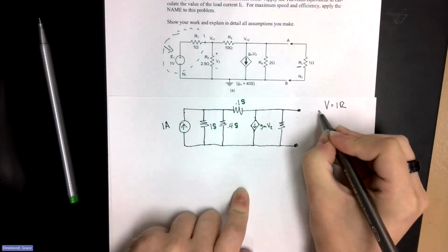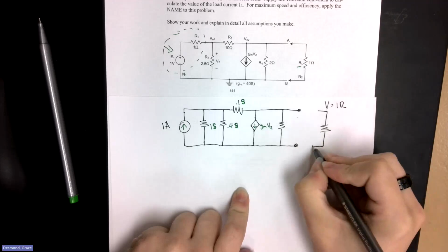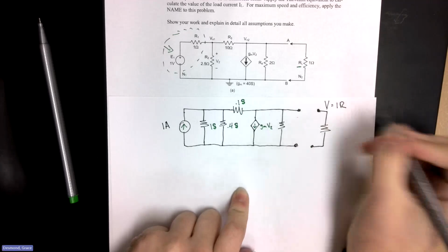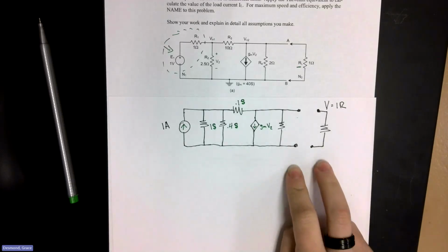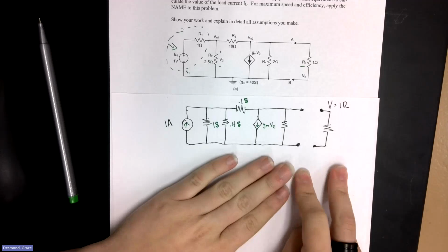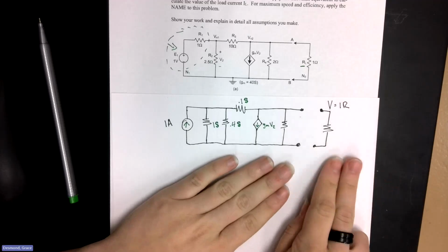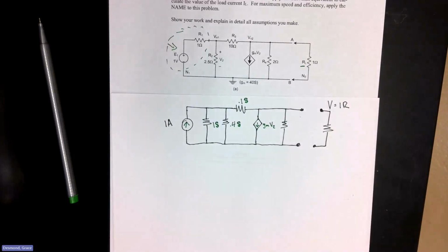And then I'm going to do what Russell did as well, and do this over here. So I'm not going to connect them. The reason I'm not going to connect them right now is that when we find the Thevenin equivalent, we don't apply that load resistor as part of it. That load resistor can change, but we don't want the equivalent to change. If the equivalent changes, then what's the point of it?